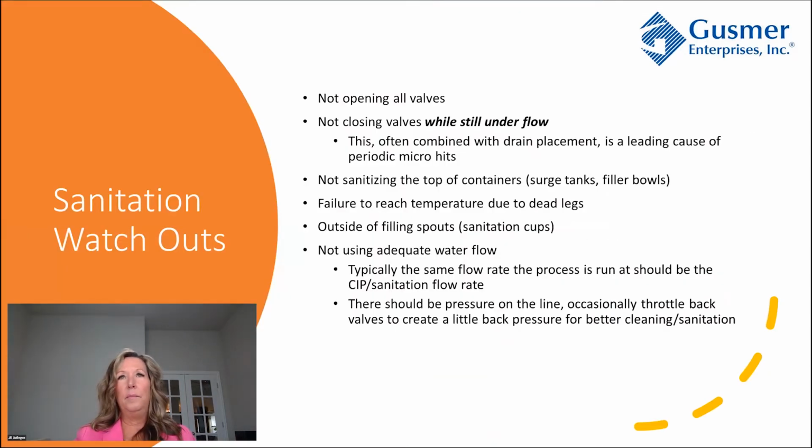So these are some things that you just kind of want to watch out for during sanitation. So not opening all valves, not closing all valves while they're still under flow. This combined with drain placement is a leading cause of periodic micro hits. Not sanitizing the top of your containers like surge tanks.